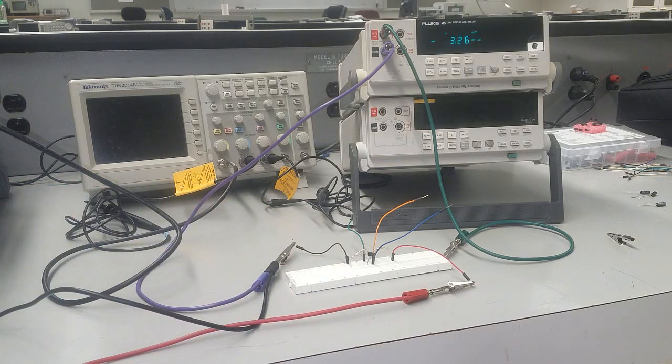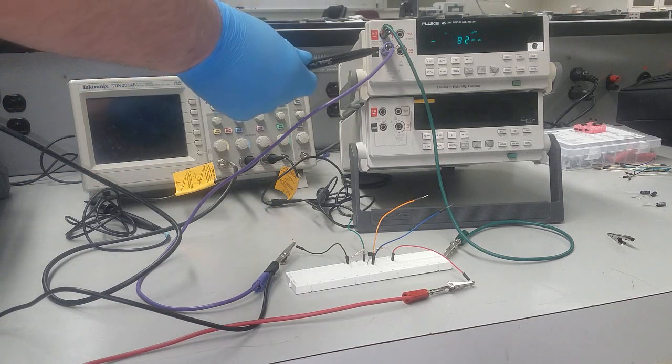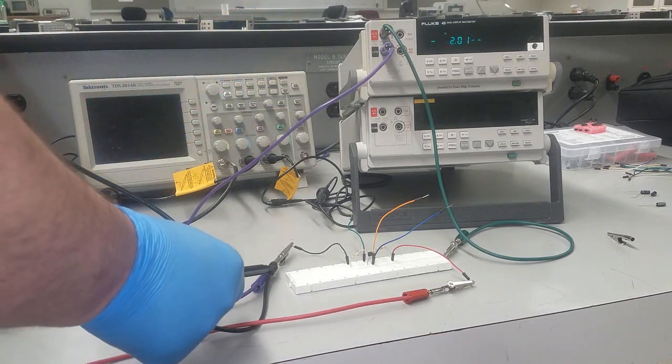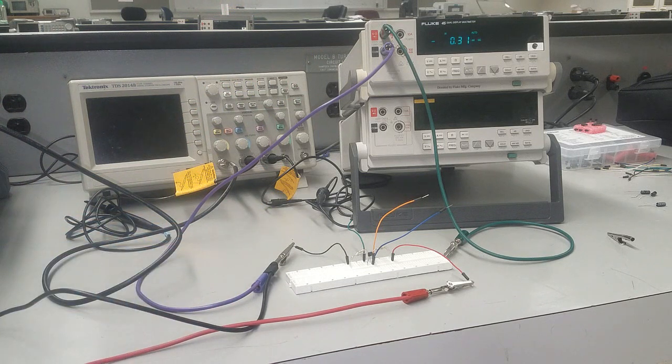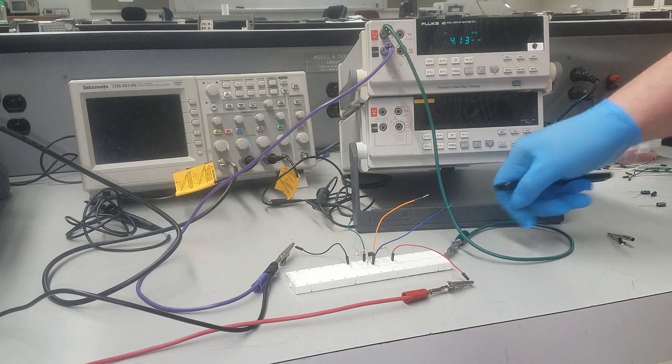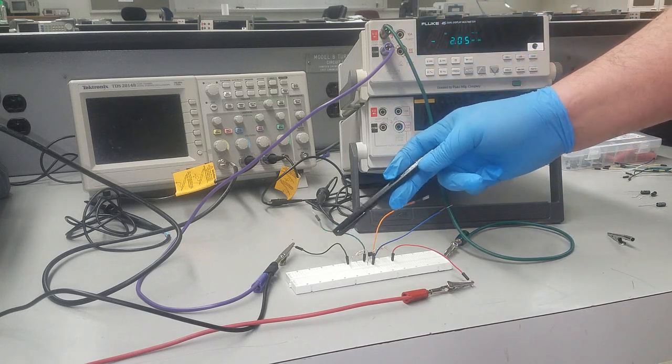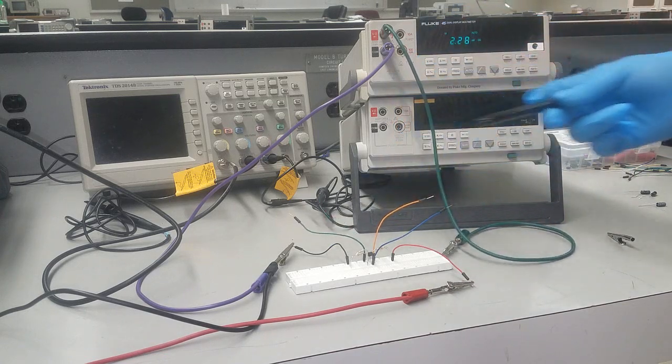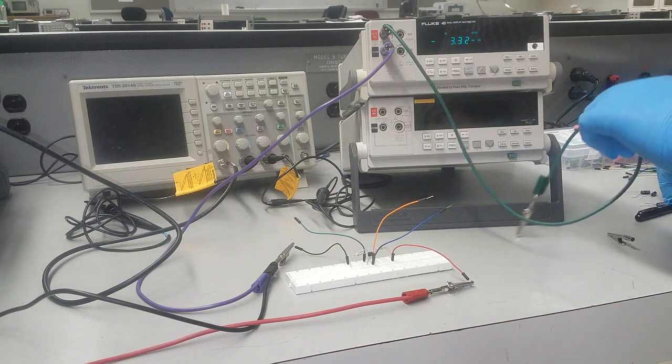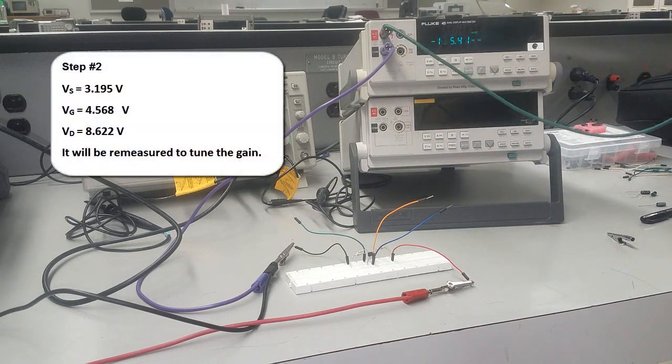And then I use the DMM. So this purple wire is the common, is the ground, and I'm connecting it to ground here. And the green wire will be able to measure the voltages at different nodes. Here I'm interested in 3 measurements. So the first measurement is the green line, and that's the source. Based on the design value, the source should be around 3 volts. It's going to be a little bit off, more or less, but it should be around 3 volts based on the calculations that we have.